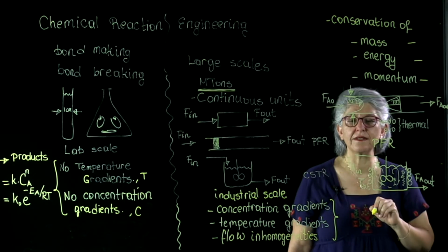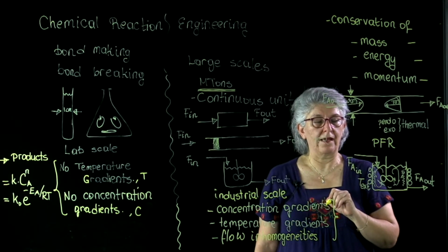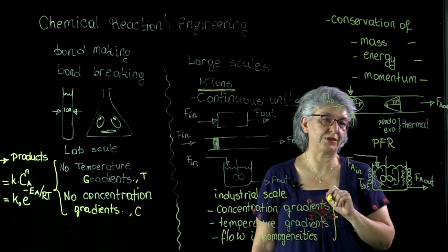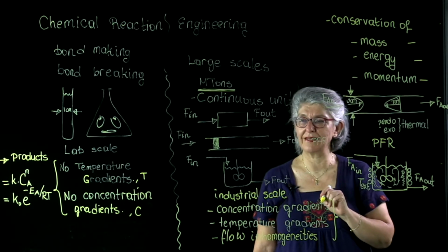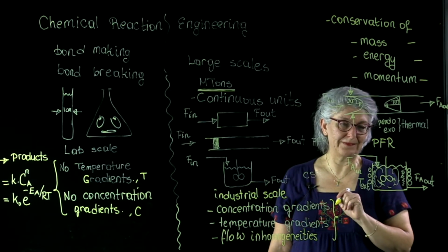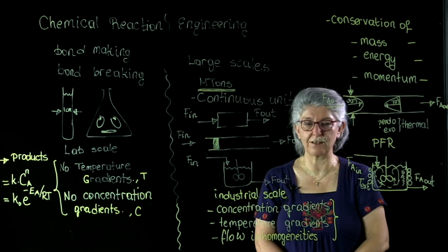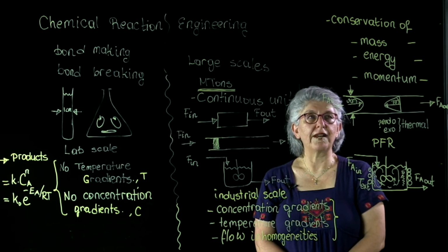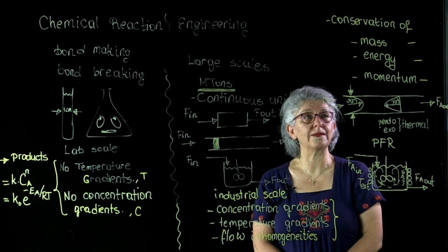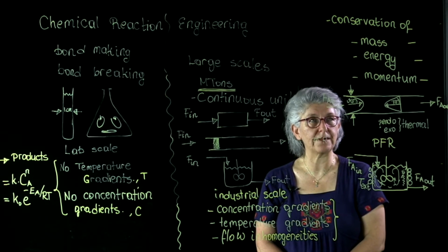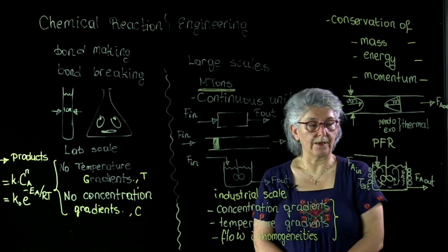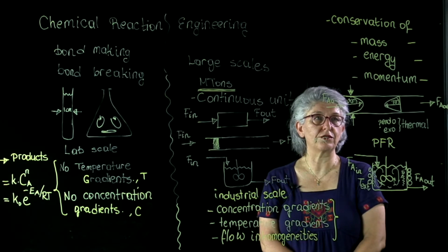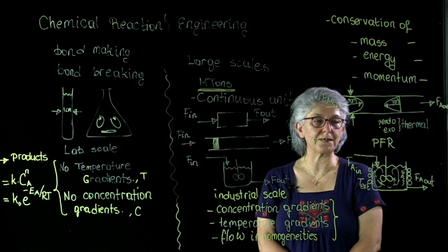Under such conditions, we may not be able to use the uniform concentration assumption as we have been using in the lectures when we were teaching you this subject as undergraduate material. Therefore, we have to solve mass balance, energy balance, and momentum balance simultaneously. However, solution of those three conservation laws simultaneously is a non-trivial problem.